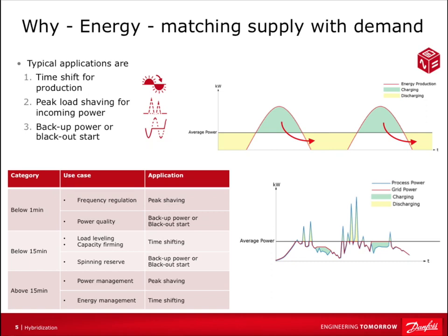It's also possible to do, for example, a peak shaving that may be considerably longer. In this case, we may have a period where the wind has completely died down for a much longer period of time, and we need to be able to compensate for that. So again, we're looking at much longer time cycles. These time cycles are critical because it is a requirement that we look at this time cycle to determine what type of energy storage best suits our applications.